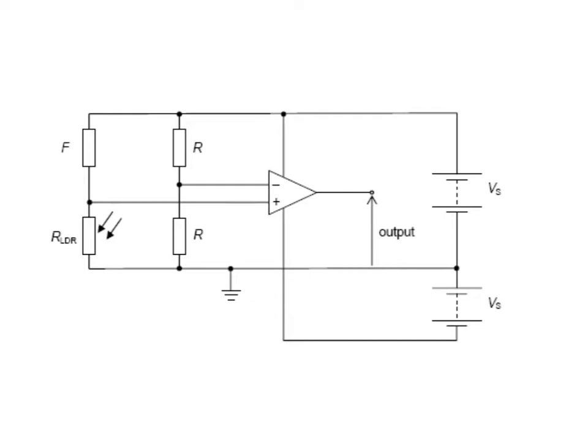The trick is by using two sets of identical batteries. Two battery cells. Make sure, for example, if this is 9 volts, this also must be 9 volts. And then the technique is to earth the center. That means in between these two cells, which is here, you earth it. So if you earth it, what is the potential here?